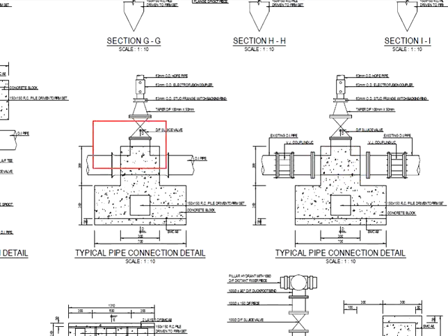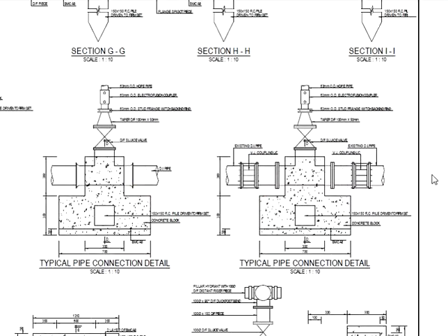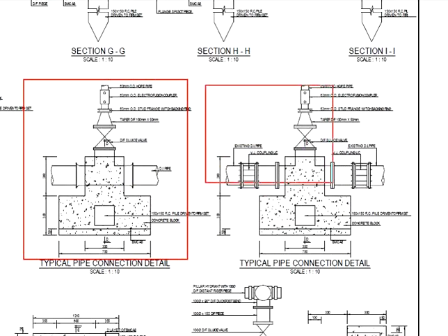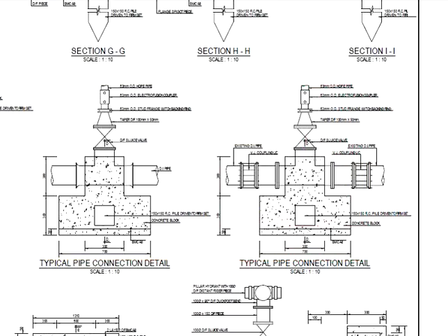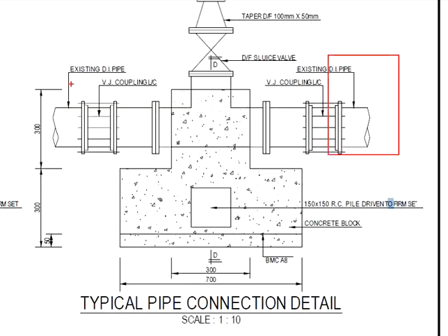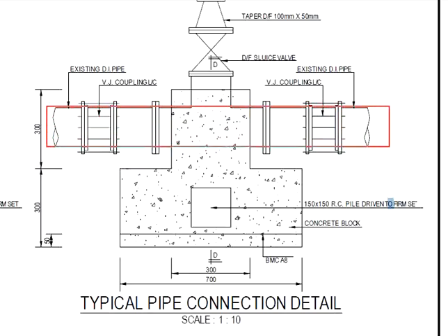Now the main difference between this and this will be the type of the joint. This is for the flange joint, and this is for the spigot joint. The rest will be similar. Compared with this one, it is slightly special. If you see the detailings here, this pipe is most likely an existing DI pipe. That means initially you have one existing pipe passing through here.